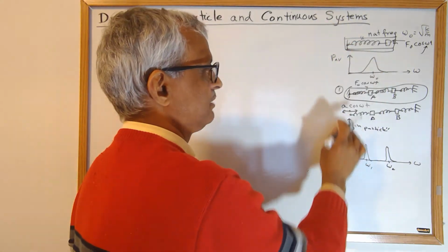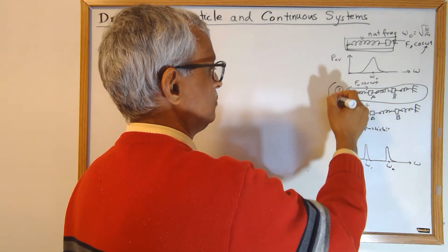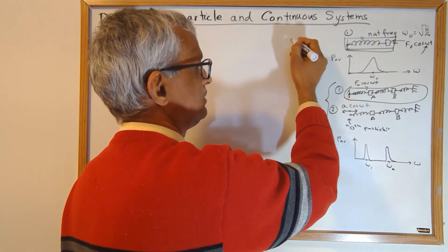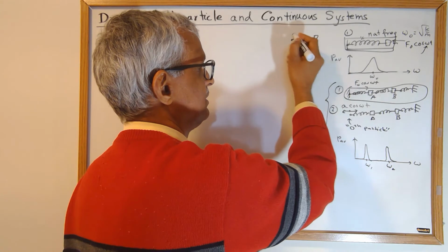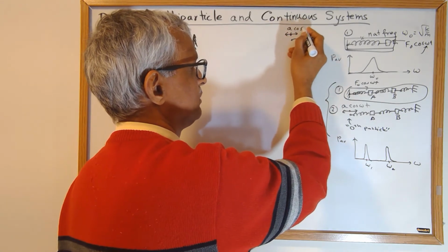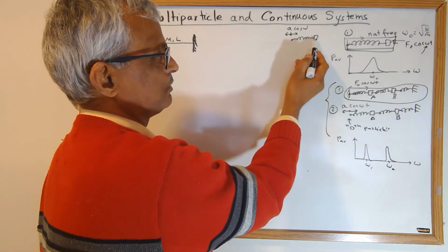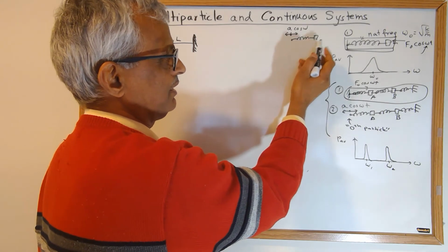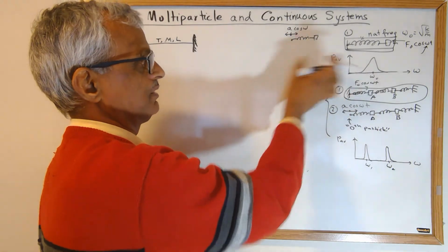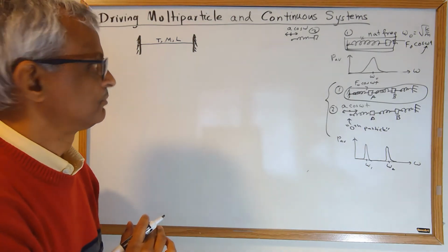Here I didn't complete it, but you had one way, and this is the second way for two systems. You could apply force on this, or you could actually do the displacement here as well. So if you move this one some a cosine omega t, this displacement will end up in the equation of motion for this one, and it will act as a driving force in the equation of motion. So this is the second way of doing the same driving.